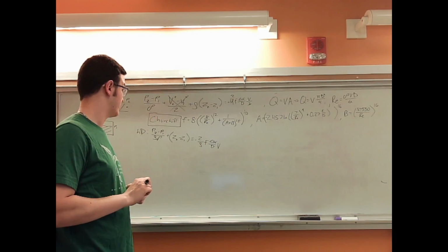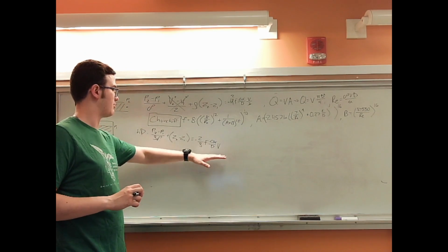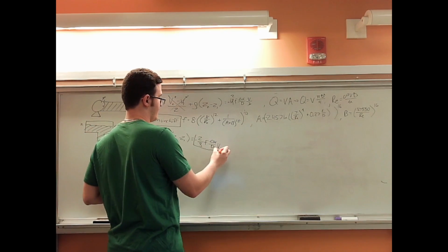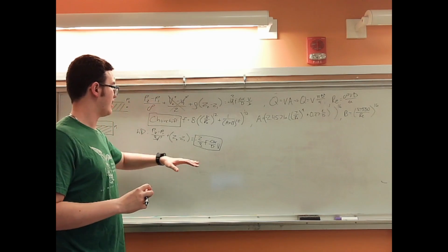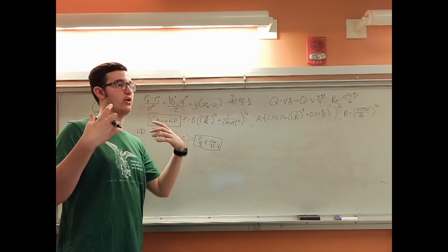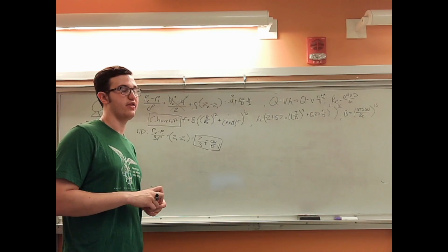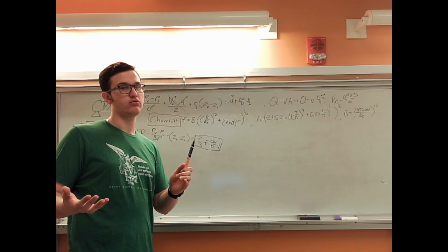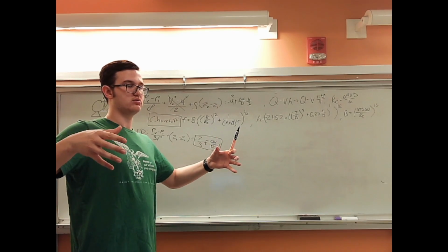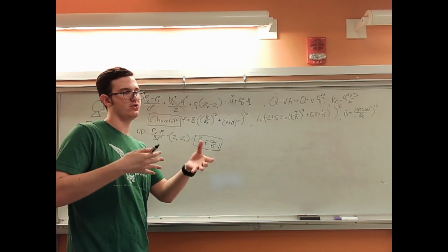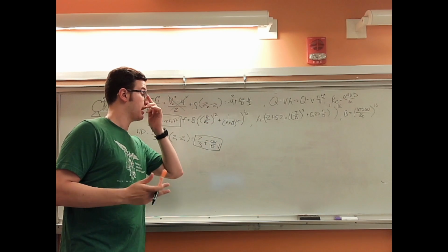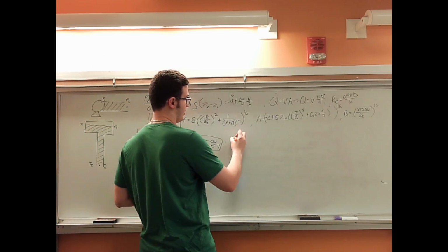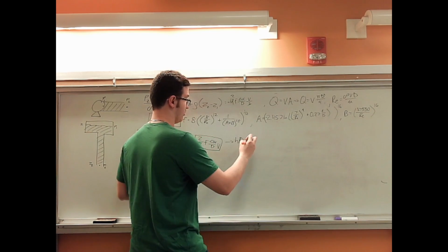So we have this, and really the head drop is just here. This is all we need for the head drop. Because if we have this, we can code out a head drop equation, and then give it a guess for a head drop, and later use a root solver to change our flow until we get to that true head drop.